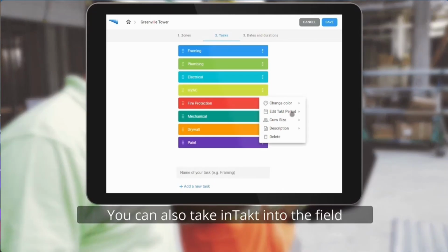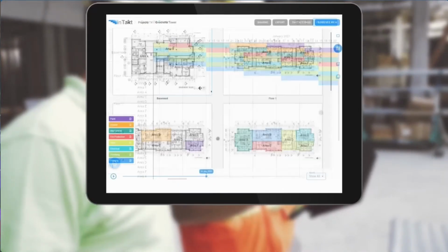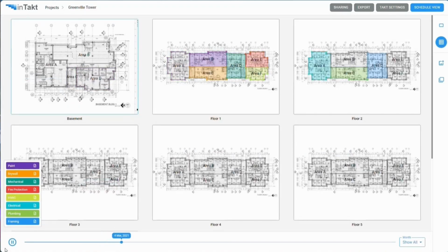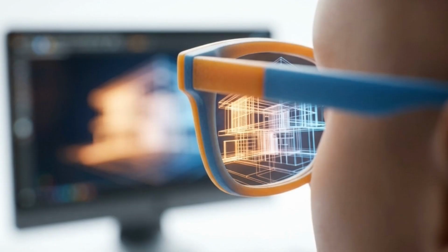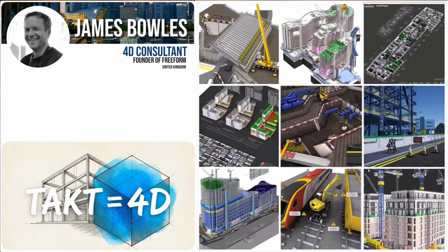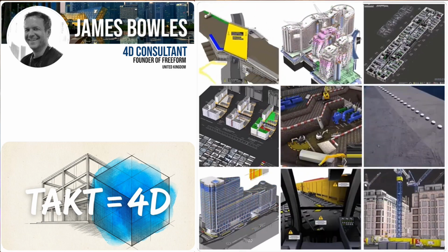The GC establishes the master schedule and then plays a trade contractor support role to remove barriers to enable trade flow. Now, here is where the true magic happens. Takt planning is incredibly visual within Takt tools, but when you map Takt sequences directly to a 3D BIM, you unlock 4D visual planning. 4D adds the element of time directly onto your physical elements.